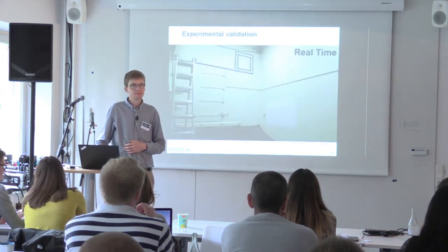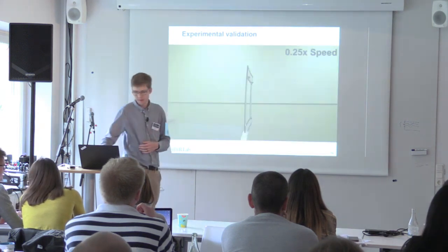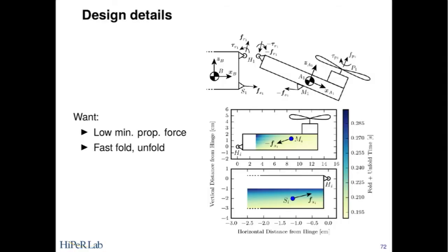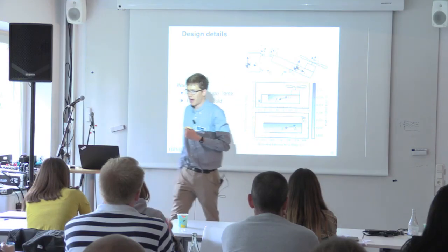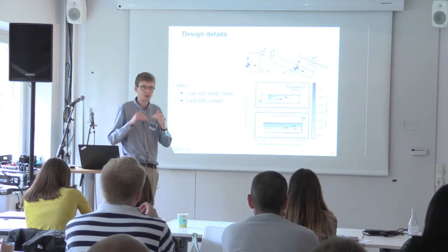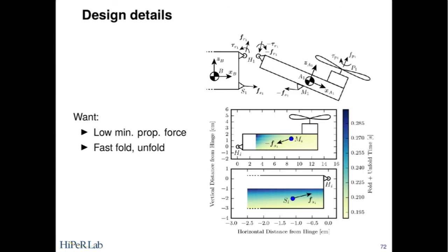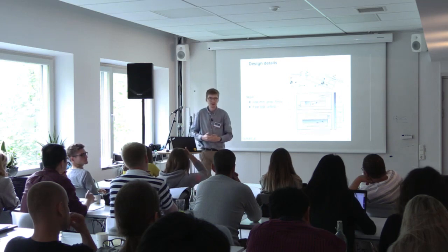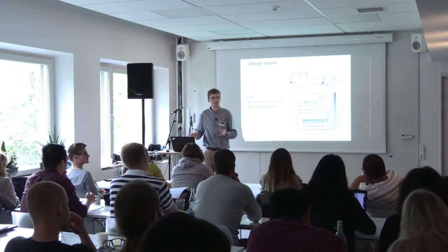You have a value lower than which it closes. Exactly. So when you look at this graph, the question is, is it hard to control when it's unfolded? There's an additional constraint that you have to respect, which is that if your force drops below some particular value, then the spring, as it's supposed to, pulls the arm in. So you have this additional constraint, and what that does mean is that you reduce the space that you can fly in as a normal quadcopter. So you do pay a slight price. It's not particularly hard for us to handle because you already have a minimum thrust, which might be 0, but there is some minimum thrust, and you're just pushing that up. So conceptually, it's pretty easy to deal with, but it does reduce the envelope of acceptable controls.